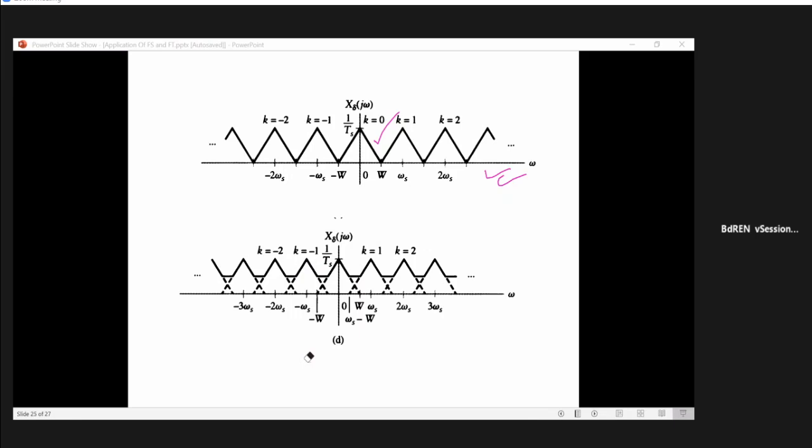For this reason, if you want to avoid this, you have to pre-process your signal before sampling. That is, you have to use an anti-aliasing filter to eliminate the possible aliasing. Theoretically, someone can say we do not need any filtering, we can just increase our sampling rate to avoid possible aliasing. But this is not feasible actually.